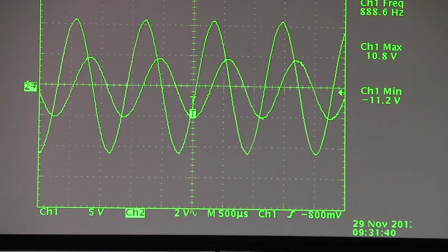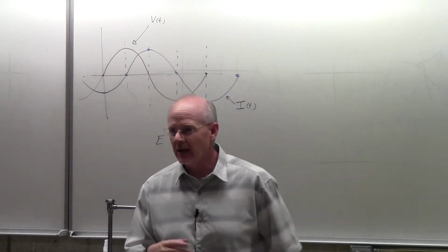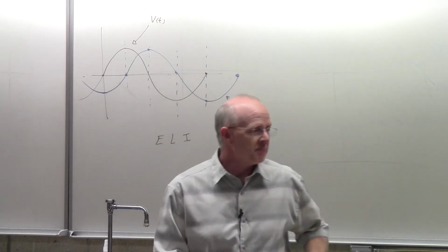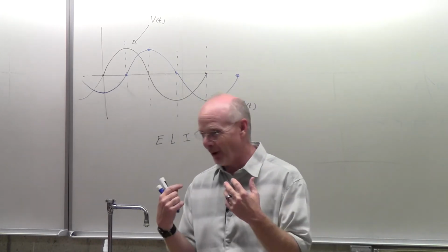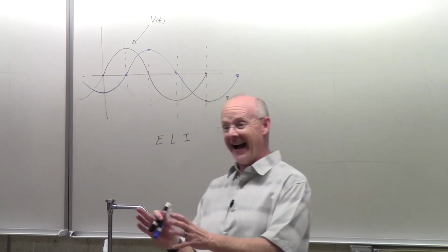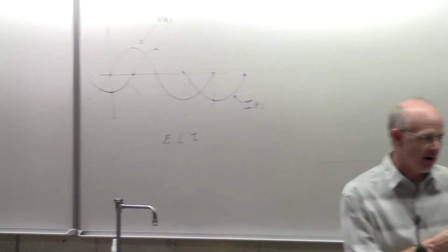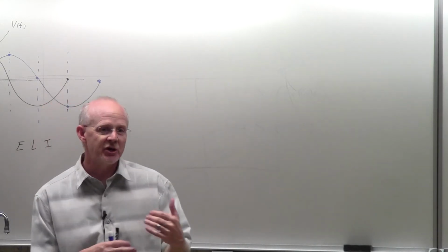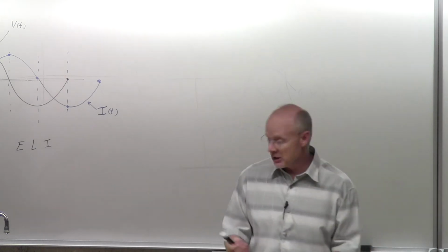And we didn't have that for the resistor. The resistor was boring, and because of that, not really as useful or creative in building things. It's because it always just does the same thing. The resistor's voltage is in phase with the current, and the current's just voltage divided by resistance. It's nice in this sense: if you have to study it or do a homework problem or a test problem on it, that's nice. But it's less interesting because it doesn't change the amount of current based on frequency, and it doesn't shift the phase between the voltage and the current. And so that inductor will.